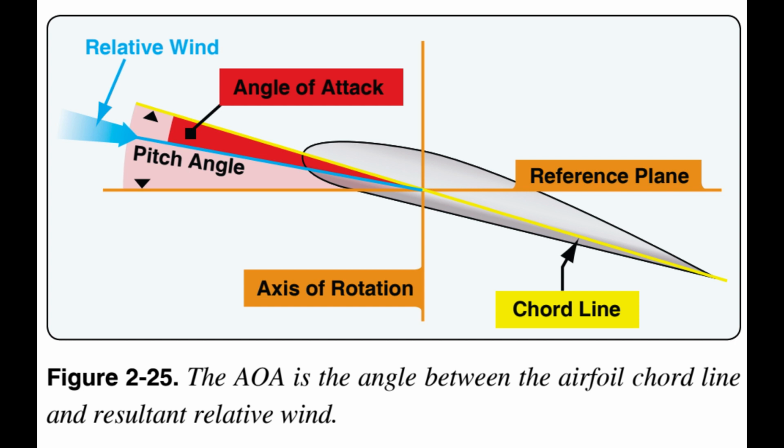Cyclic feathering changes the blade's AOA differentially around the rotor disc and creates a differential lift. Aviators use cyclic feathering to control attitude of the rotor disc. It is the means to control rearward tilt of the rotor, blowback, caused by flapping action and, along with blade flapping, counteract dissymmetry of lift, discussed in Chapter 3.